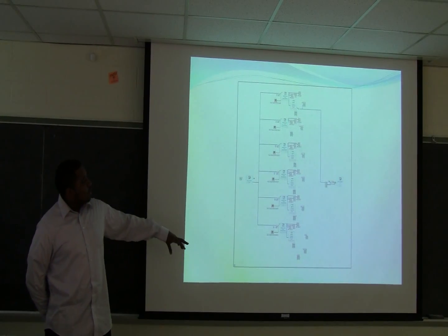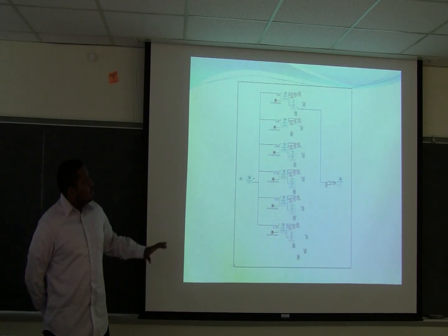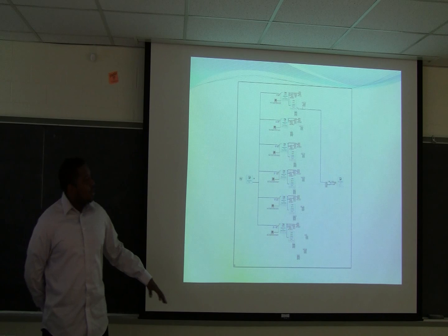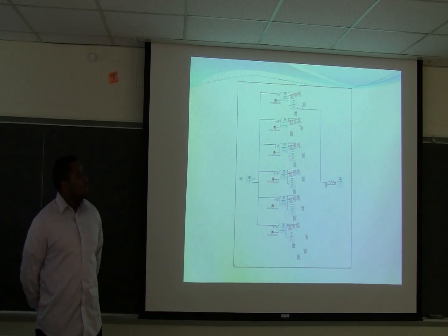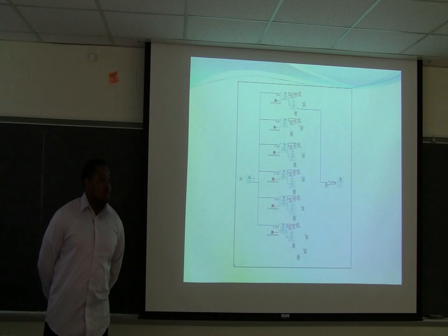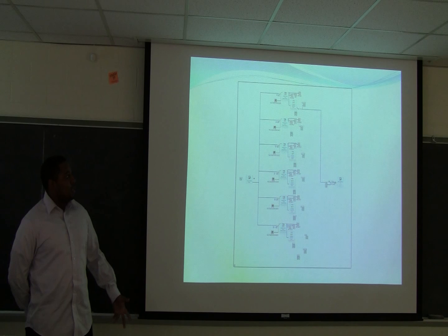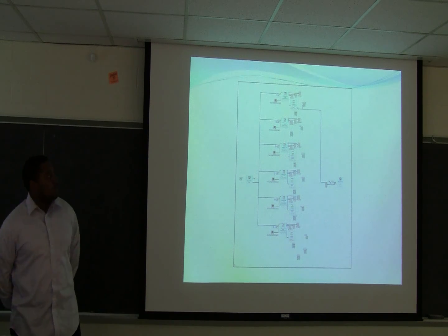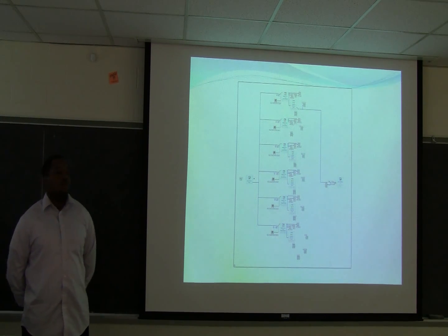It takes the 6 different inputs, does some comparison, and then sends out digital outputs depending on what switches the user has pressed. For the RMS voltage, if the utility is no longer on, it will automatically switch to our system. Or if the user doesn't have the load 1 switch pressed, load 1 won't be on.